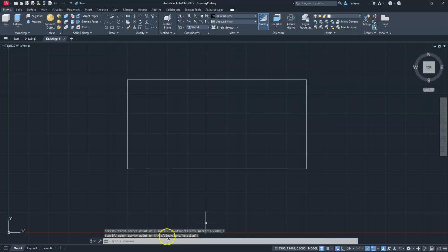So that's what I'm reading down here on the command line, right? Now you see that this rectangle is created. There is no way of changing this rectangle unless I come back in and redraw it or do some manipulations like stretch it. But AutoCAD has got to be super accurate, so you have to put in the dimensions of that rectangle right here in the beginning, okay? And I cannot come back and change it once I'm making an extrusion without doing, I guess, some other drastic measures. So it's not as simple to edit this on the fly.